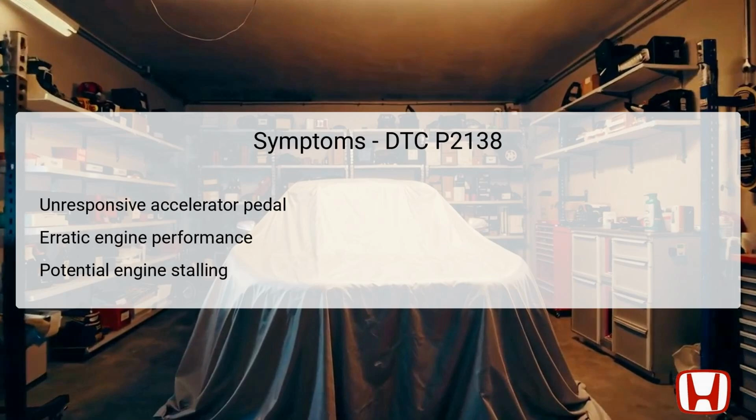vehicle's normal function. DTC P2138 can manifest a variety of symptoms that may affect the driving experience. One common symptom is an unresponsive accelerator pedal, where pressing the pedal does not result in the expected acceleration response from the engine. This can create safety concerns, especially in traffic or during merging situations. Additionally, drivers may experience erratic engine performance, including accelerated or reduced speeds without input from the accelerator pedal.